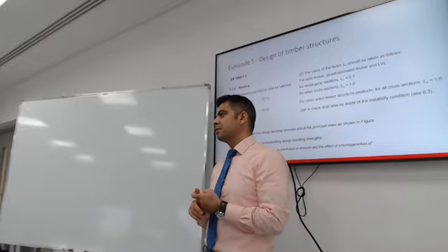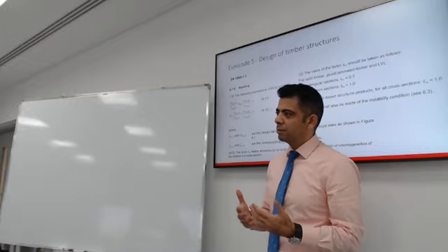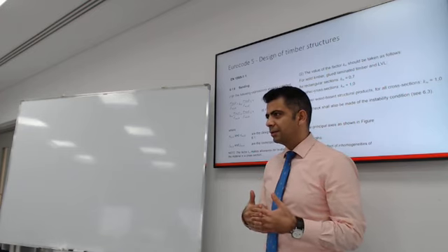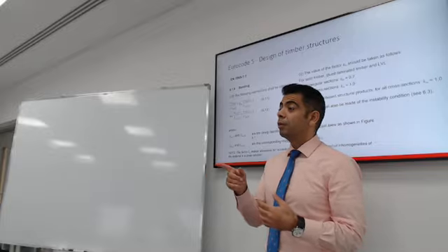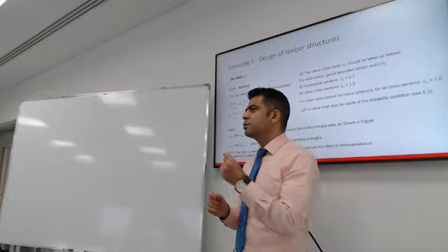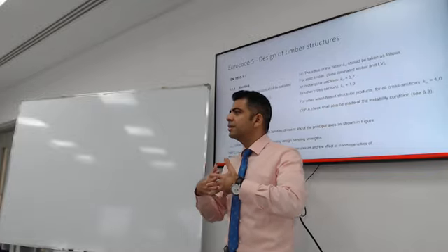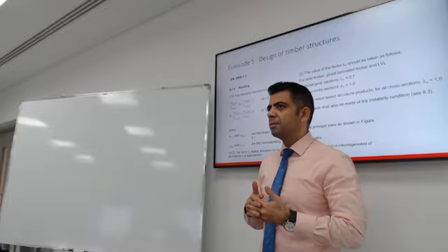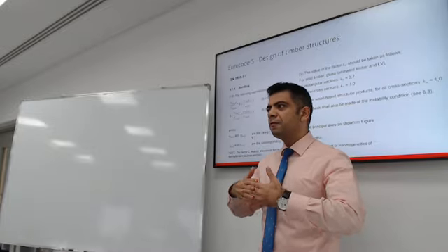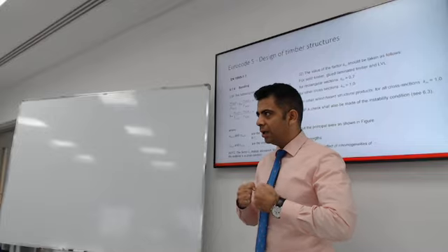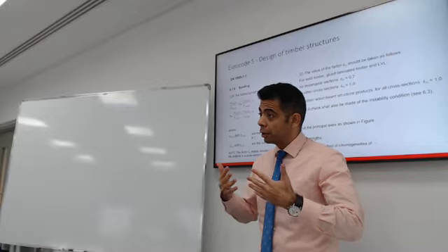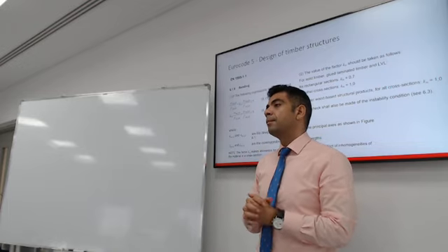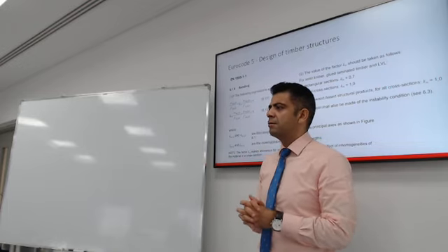Yes, you definitely need the section modulus, but is it going to be the plastic section modulus or the elastic section modulus? Elastic. Why is that? Because wood does not yield. The plastic phenomenon is only for steel. Steel is a very interesting material because it doesn't fail suddenly. It will retain its strength over large deformation. That's what a plastic hinge is. There are very few other materials that have this quality.